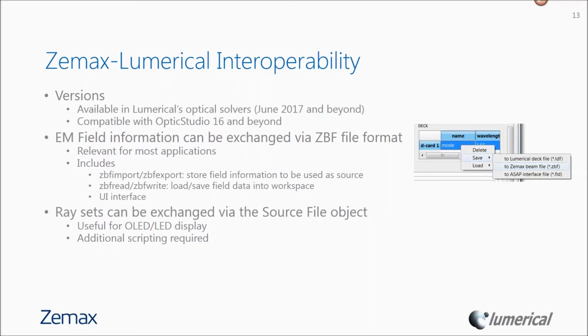And the same goes for other formats. For example, if you want to simulate a rough surface with an EM solver and extract the BSDF function from it, you'll also need to do a bit of post-processing to get the data in a format that can be read by OpticStudio. We're very happy to provide some sample scripts to help you do this. And depending on the type of feedback we get from end users, we would certainly like to build this directly into our products in the near future, so you don't have to do this additional step.